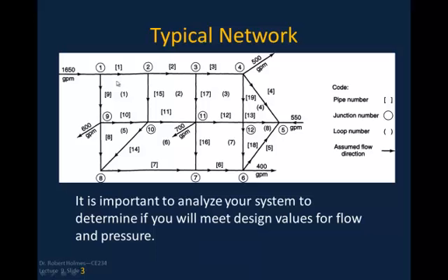And so the key is, how do we solve the problem where we have flow coming in, flow going out externally, and then we want to know what is the flow in each one of these individual pipes. You can see that they're interconnected, and it takes some iteration scheme that we put together in order to solve for this, and the HardyCross is going to be the method we're going to look at.